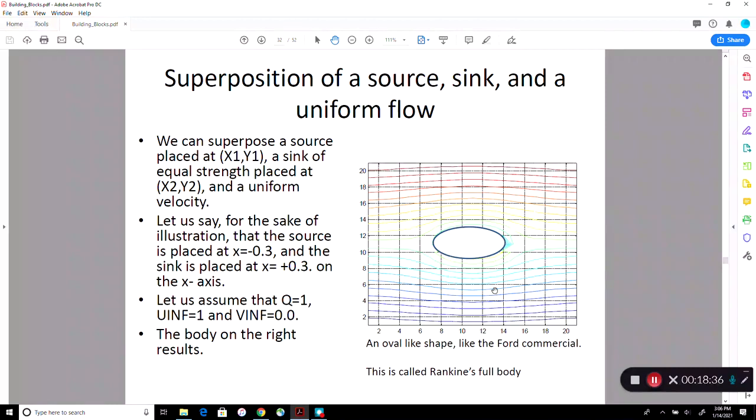But D'Alembert said, wait a minute, if I put an oval-shaped body in the air, I will get a drag. So this is a paradox, D'Alembert's paradox. But in reality, you have a boundary layer that causes skin friction, causing drag. You get a separated flow at the back end of it, like a flow over a bluff body, like behind your car, for example, or a cylinder. Therefore, you get in general lower pressures here compared to the front, so you also get a pressure drag.